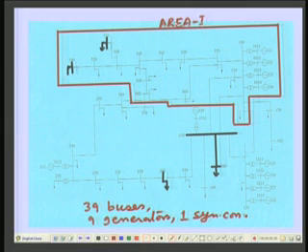Now, here in this area, some buses which are likely to suffer the voltage instability problem are identified. The buses which are very far off from the loads are like, say, 530; this bus number is 530. This is one typical bus which has been identified. Now, for this system, the first step which has been done is to plot the VP curves for this multi-machine system. How do we obtain the VP curve?